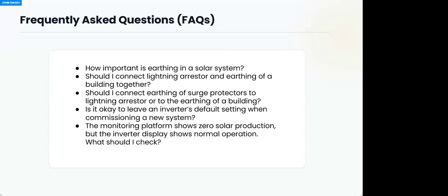Now the cable that will be used for earthing also plays a vital role in this case. You cannot use a tiny cable, for instance maybe 1.5 mm, from the roof to the ground for a lightning arrestor. You have not arrested anything. In fact, you have opened more room, because by the time the rush comes from the roof, it will just be wasted along the cable, or the cable even gets disconnected or hot because of the current, because of the lower gauge. And when that happens, it's useless. It's not working.